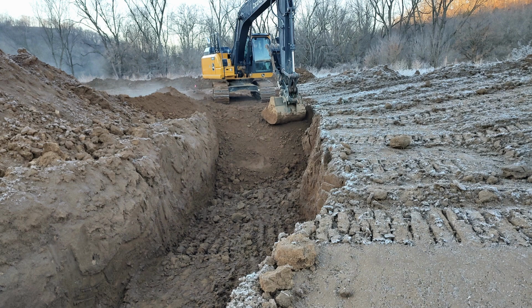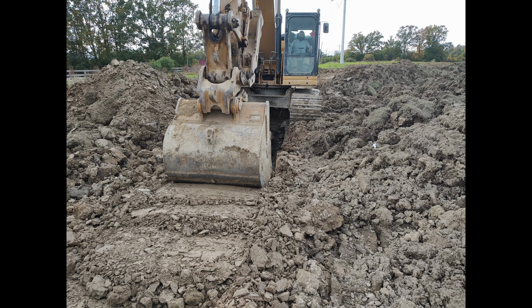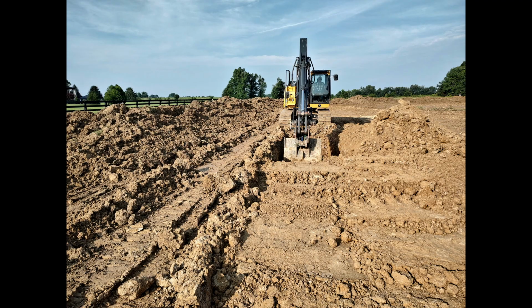When a dozer is not available, you can use an excavator to place and compact the soil in a core trench. The clay texture soil that's removed from digging the trench is mixed using the bucket on the excavator and then returned to the trench and compacted in layers to form the groundwater dam. Here the excavator is using its bucket to compact a layer of soil that was placed in the core trench. This process takes time and it's less efficient than using a dozer and an excavator.